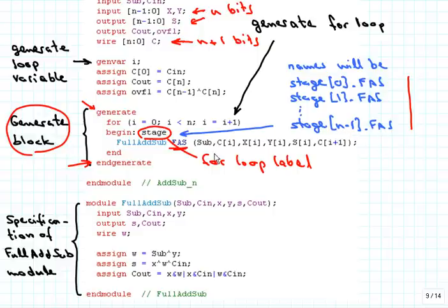And the way we specify here the connections of the inputs and outputs of those stages is pretty much the same as we would if we had instantiated all those copies by hand, except that it's now indexed with the index I. So SUB, the subtract control, is going to be common to all of those 1-bit adder modules.